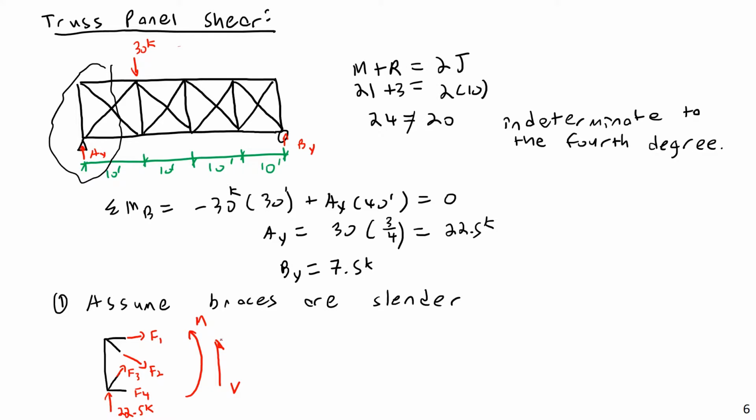Now, let's think about this here. Here is the question. Can F1 and F4 contribute at all to the shear? No. Why not? It's in the horizontal direction. Exactly, yes. That was a good quick answer, I was just seeing if you were jumping to it. F1 and F4 can contribute nothing to the shear.